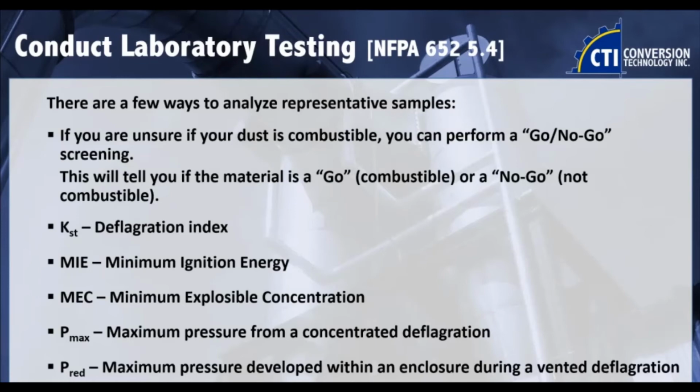So you don't need to get the dust tested because there's no potential hazard that's going to come out of it. But if you do go forward with the dust testing, or you get a DHA that recommends, hey, test this dust to know how explosive it is, does it meet the minimum ignition energy requirements of a bucket elevator, for instance, do you need to add grounding straps? There's a few tests to do.